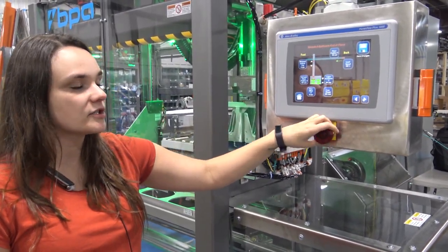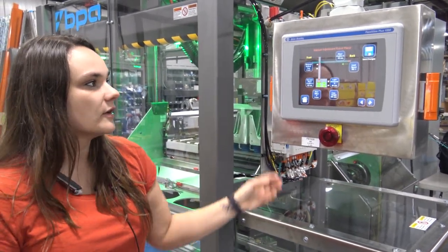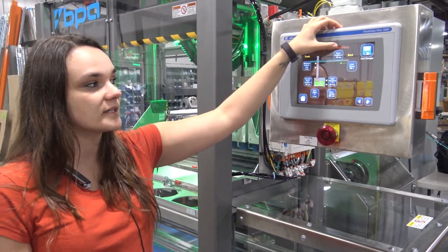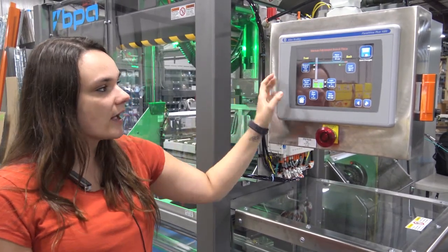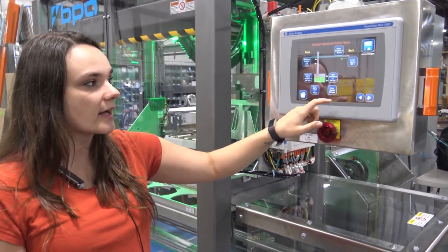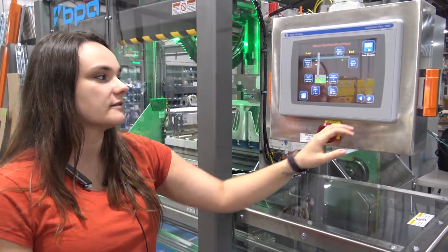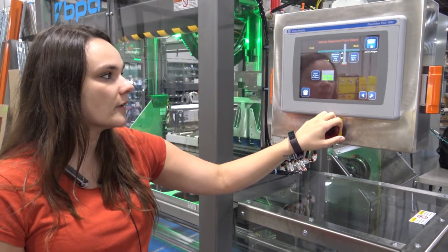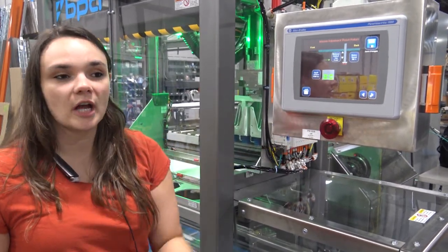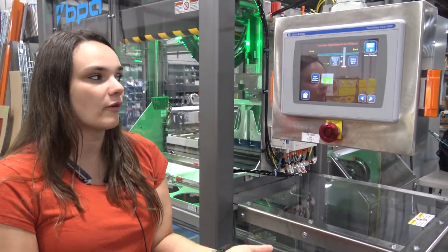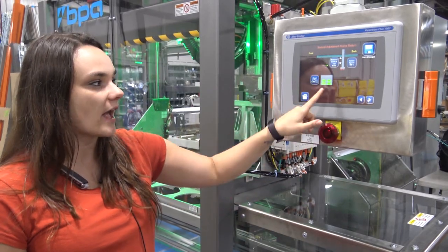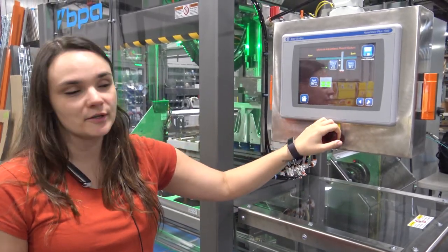This is our place position, which is where the robot is coming over to place product into the cases. This is where you put in your position to put where the cases are at, how far up your increments are, your case height, as well as your load speed. How fast do you want the product to load into the case? Then we have our robot return, which is it coming back to pick again from the Smart Track belt from the case. This is where we have our gaps, our dwells, and our return speed as well.